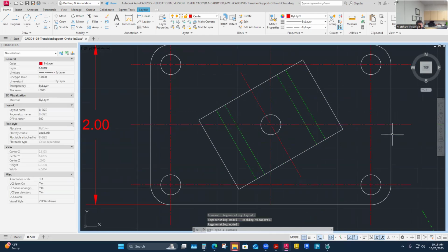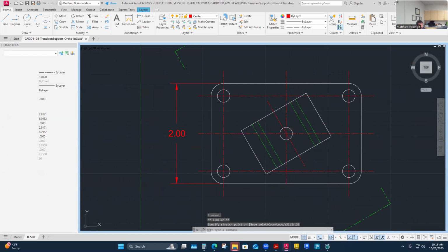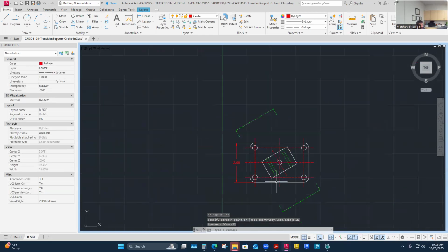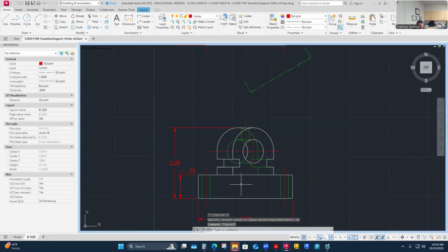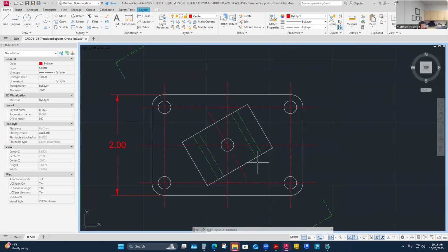So this is one way to dimension, and there's more ways because these are a nice surface to pull from. Like this surface is 3/4 of an inch tall, it's 3 inches wide. I could call it relatively flat. I mean, it is flat. And so could I pull dimensions from the front or back? I think so, yes. I could use them and not establish the center lines that I just did. The only reason I'm heading this way is because of the twist of this part. And I feel like the best way to control that twist is maybe with its own center line.